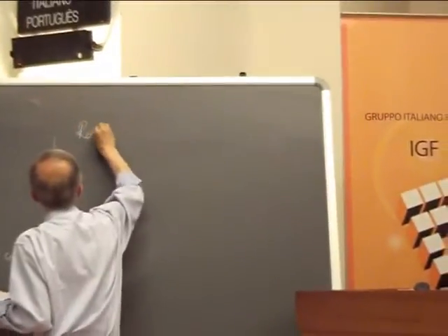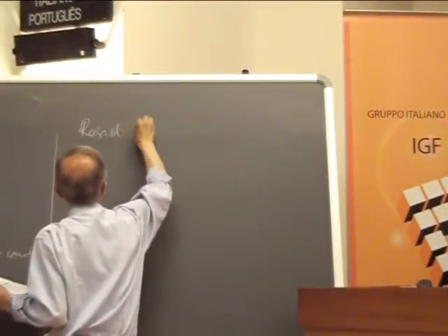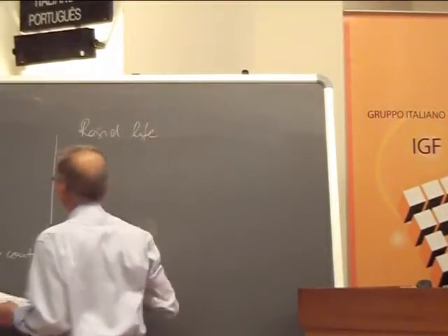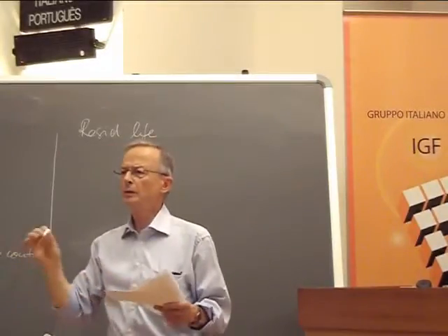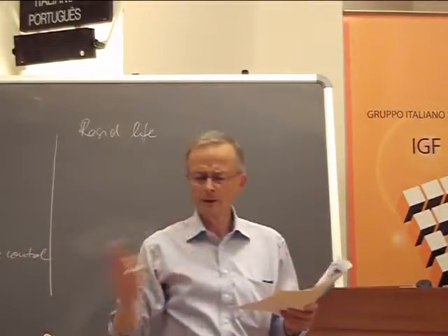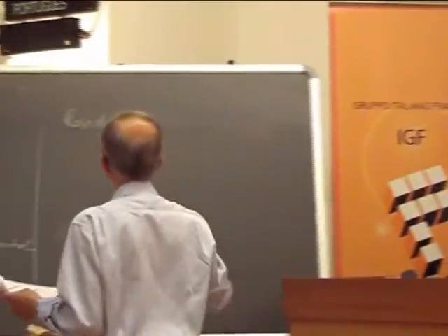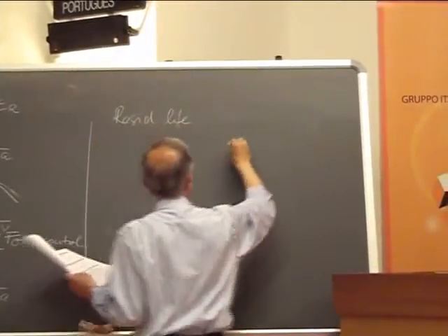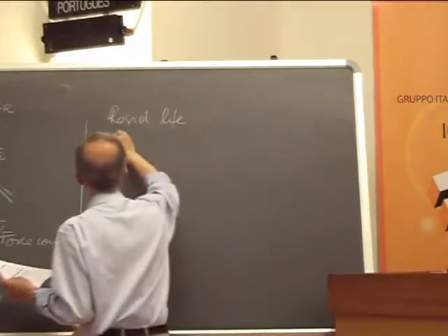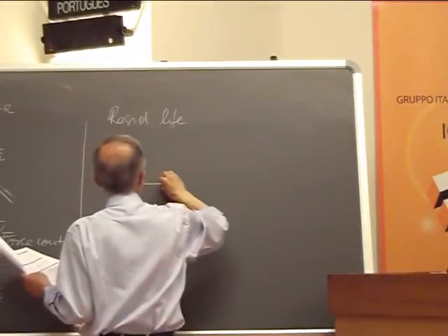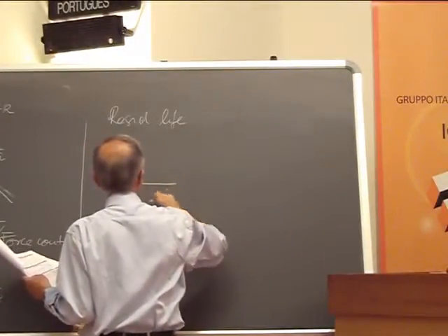And as far as residual life is concerned, residual life for a cracked component, remember we are now only talking about fatigue, forget about the other mechanisms, only fatigue. We have a crack propagation curve. How did we determine the crack propagation curve?